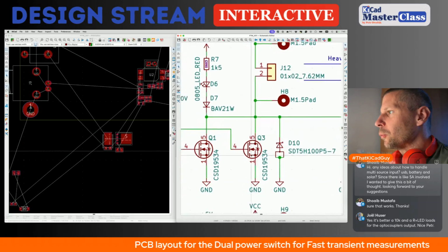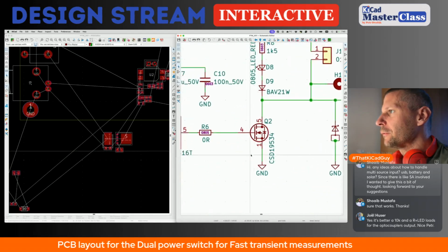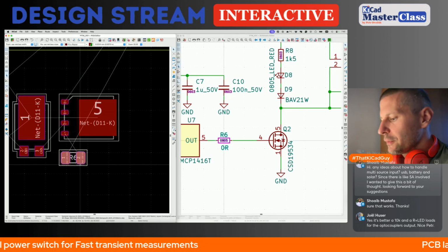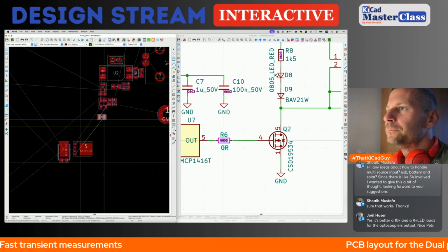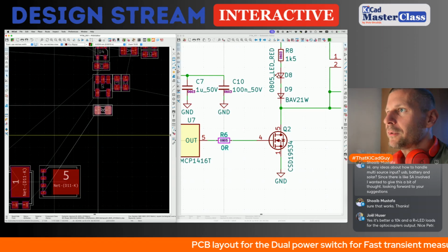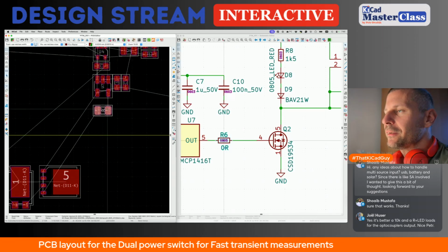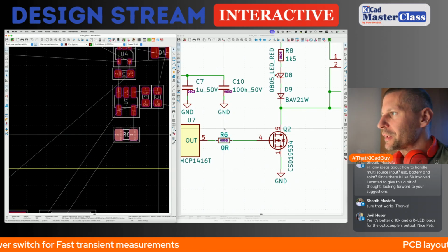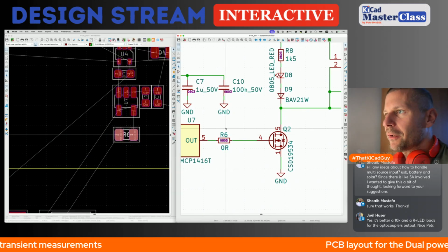Now the light load channel, this is this one. So the gate resistor can be placed here, maybe for further changing. I need it accessible for my soldering iron. This is a good position. This is why I chose the 0805.